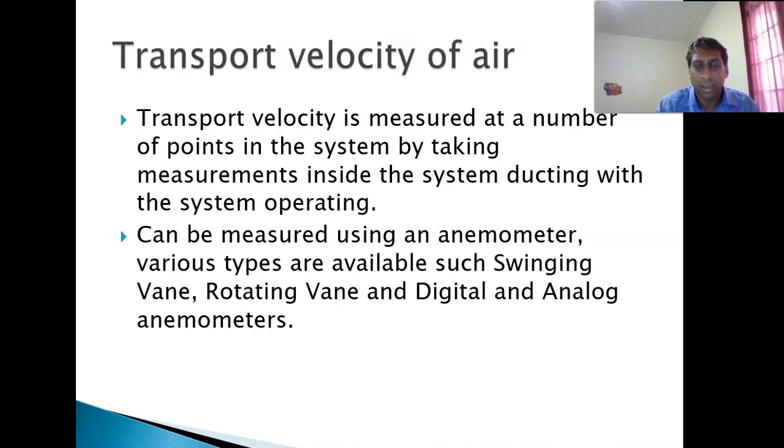Again, there are no diagrams for the exam. It's just to know that if they ask how you measure transport velocity or even capture velocity, you can simply say by the use of an anemometer, and if you're able to give a name, digital, of course, being the simplest in today's age, that will be sufficient.